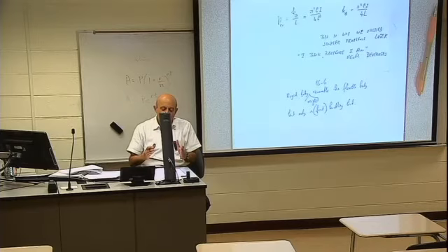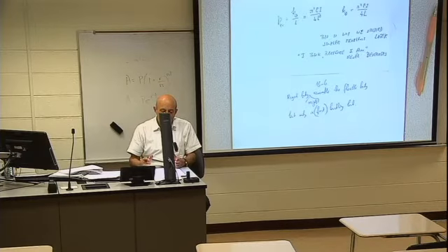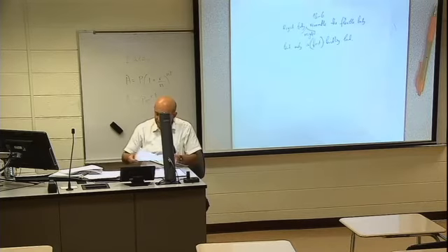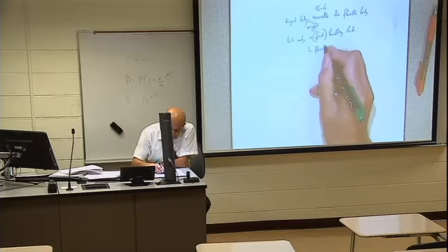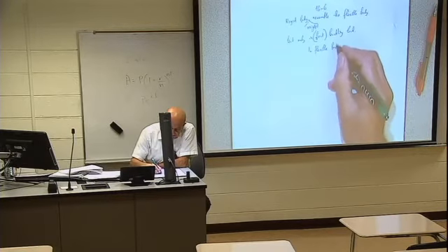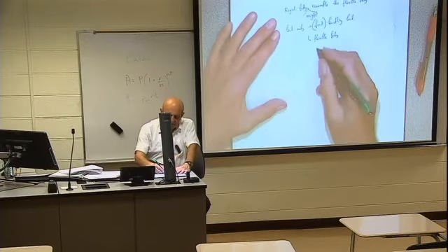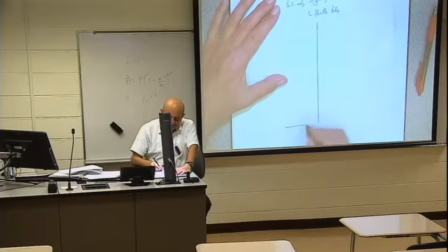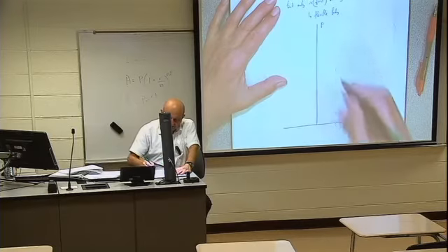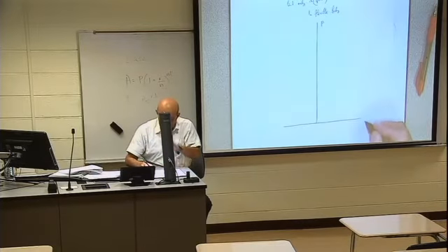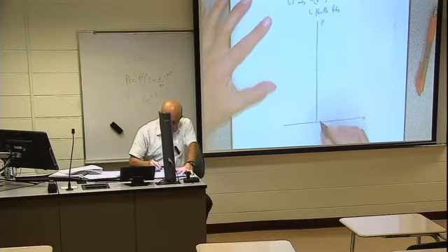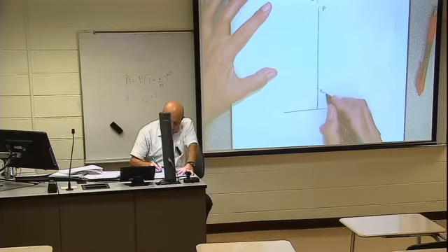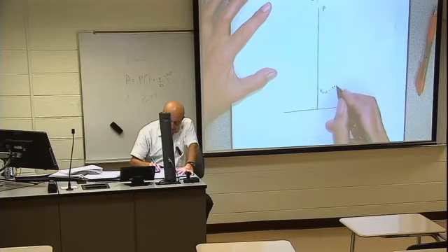Okay? We can establish a connection only with the first buckling load. In a flexible body, the displacement looks like this. That is P, that is V. So then here we have P critical 1, which equals pi squared EI over 4L squared.